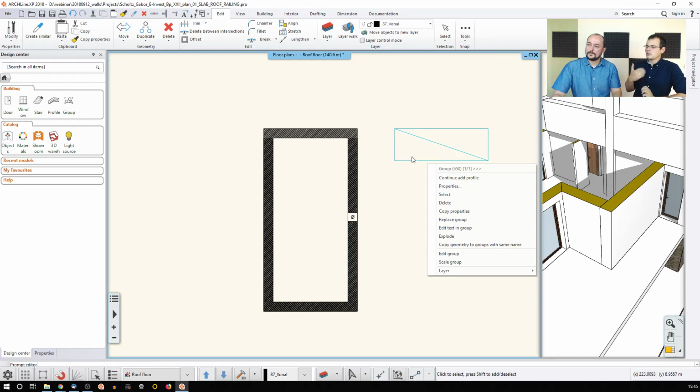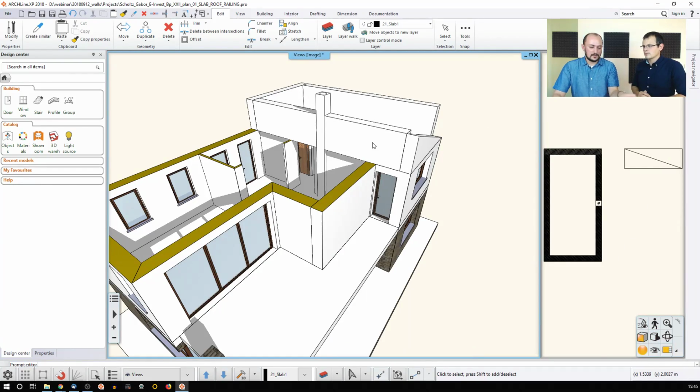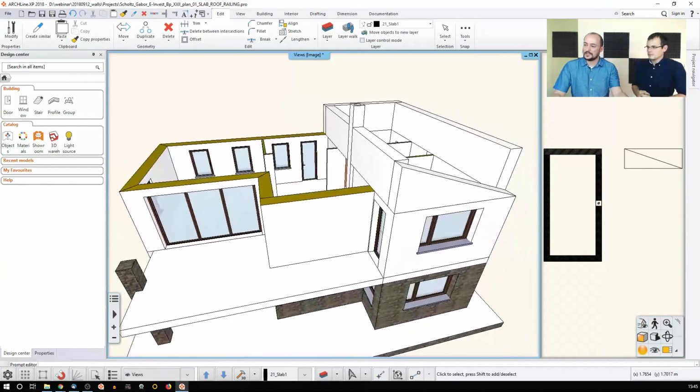And so now you redraw how it should look from the side. Again, you can use values. You can type values if you measured them from your model. You can actually use the projection of the elevation as a drawing behind this, and draft it that way. But the point here is that from this point on, the software changed the height of this wall.